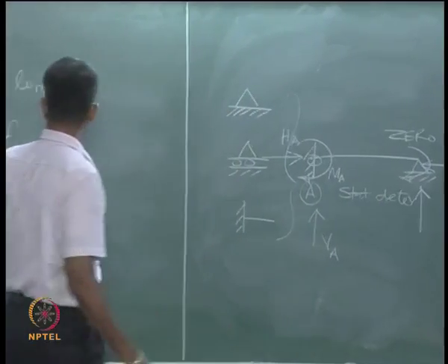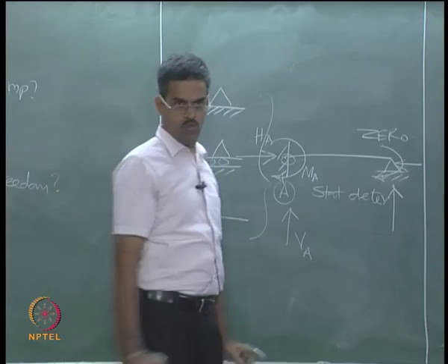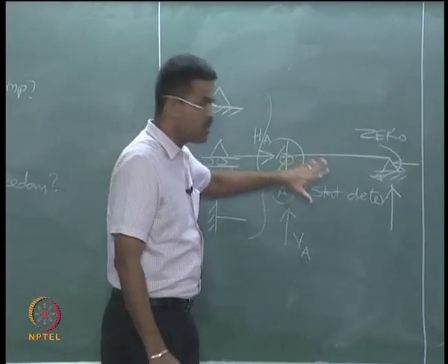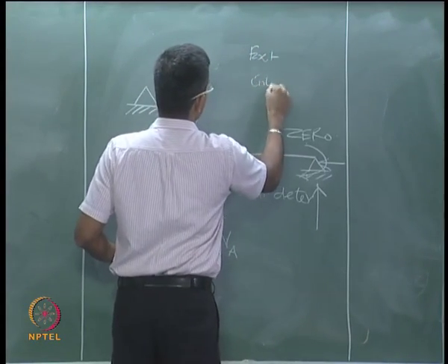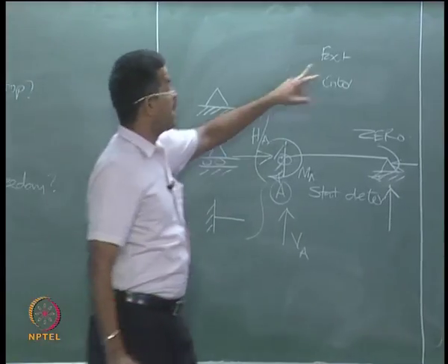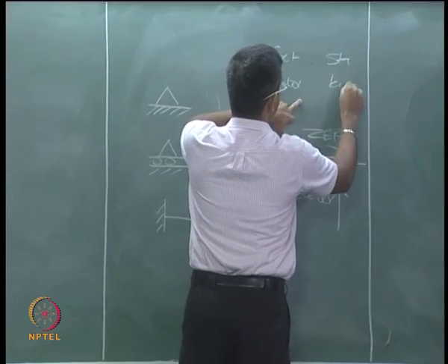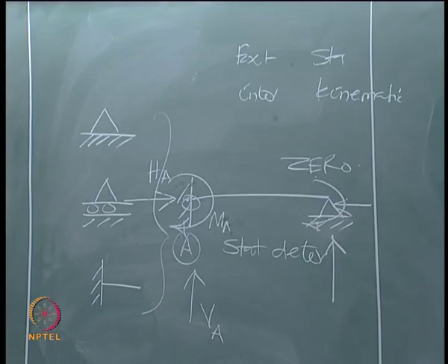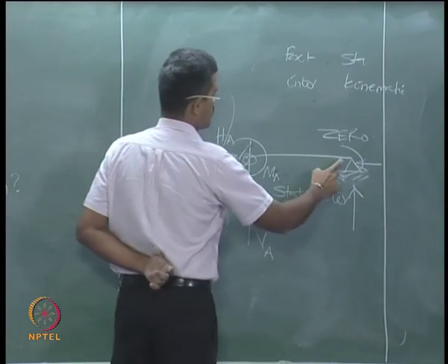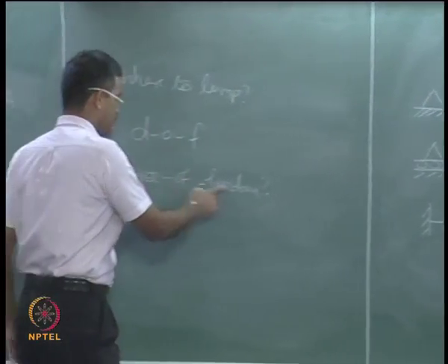So, here the degrees of freedom depend on where the support wants to move. So, it is related to displacement or action on the support. It can be either external or internal. It can be an action or it can be a reaction. One is called static, other is called kinematic. We can add them together to find total degree of indeterminacy. So, while defining the indeterminacy in a given structural system, which is based on forces or internal reaction, we also define degrees of freedom in a given member.